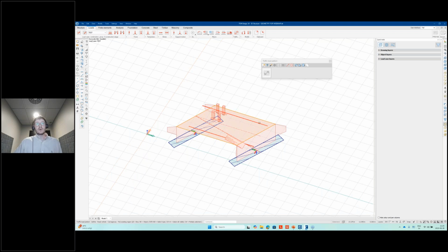So now you have your traffic load placed on your structure. Not only that, you also get all of these load cases with a single unit load placed on your structure. And this is why I recommend people to stay away from the load case option, basically, because you get overwhelmed with all of these load cases. But from load groups, you can easily maneuver around this.